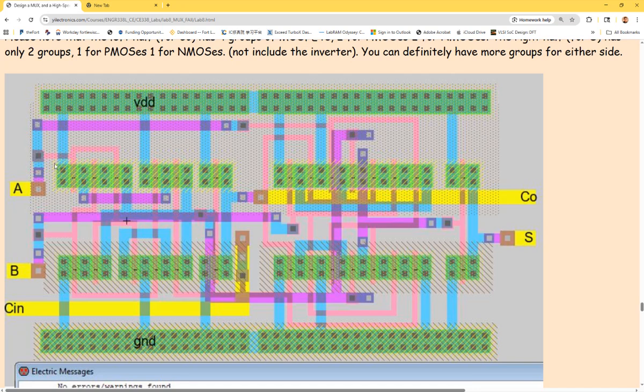You can see these are PMOSes, and these are N wells, and these are all the P well taps, P taps. Oh, sorry. PMOS are in the N well. So these are N wells, and these are the N taps. N taps have N+ in the N well. So the dots are N wells, and these are N+ nodes with vias to metal 1. You can see they are connected to metal 1. So basically an N tap with a via to metal 1.